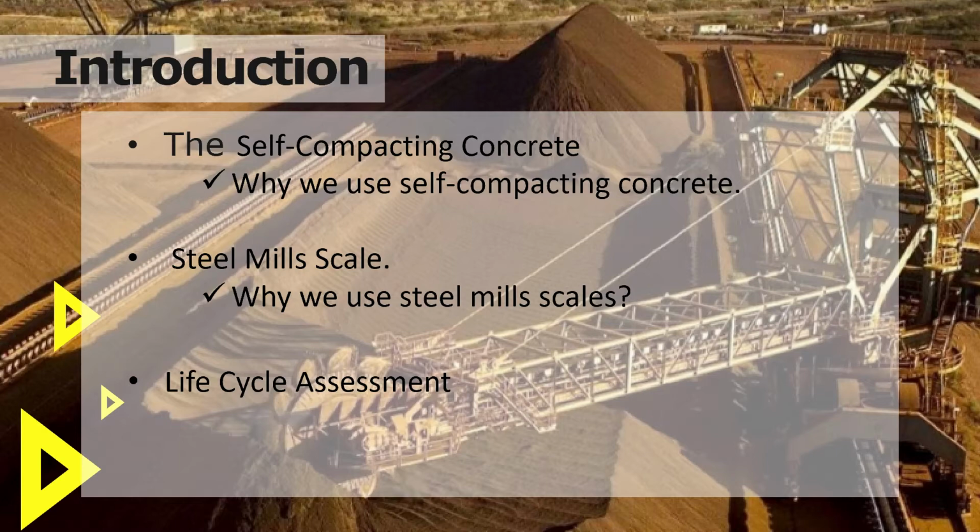Now, the next question in your mind will be, what is self-compacting concrete? Self-compacting concrete is a concrete mix which has low yield stress, high deformability, good segregation resistance, and moderate viscosity. So it does not require vibration or tamping after pouring, and it is also much less labor intensive.